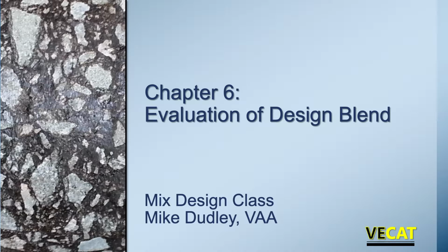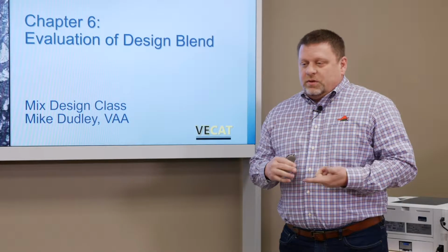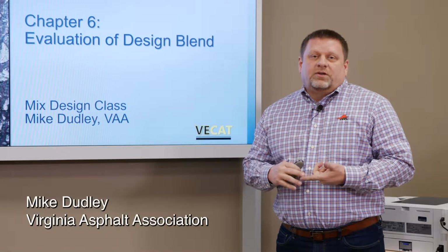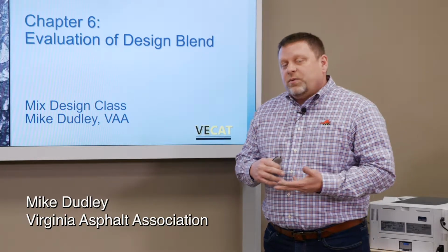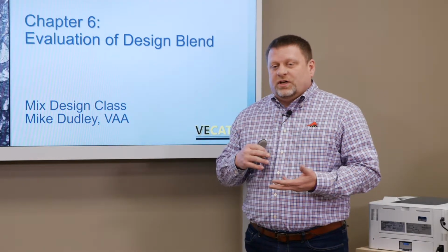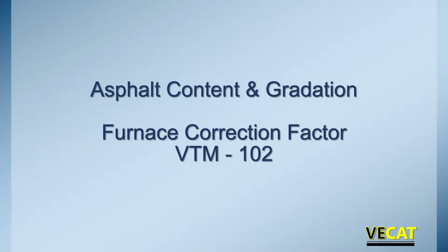I'm going to go through some of the evaluation of your design blend for the mix design class. Through this, we're going to talk about the furnace correction factor, a permeability test, and even though it's not required as part of your mix design, we will discuss TSR tests. To begin with, we'll talk about the furnace correction factor. It's for your asphalt content and gradation.